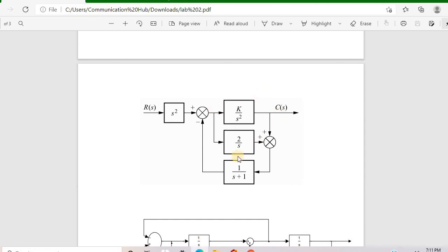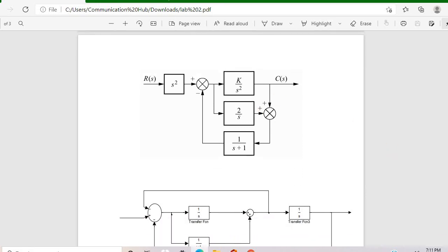So you have to think about it and solve it by yourself. And how do you verify it? Very easy. After the reduced form, give the step input to the reduced form and also the step input to this block diagram that you can easily make in Simulink using the Simulink library. So you can verify both results in the same model file.